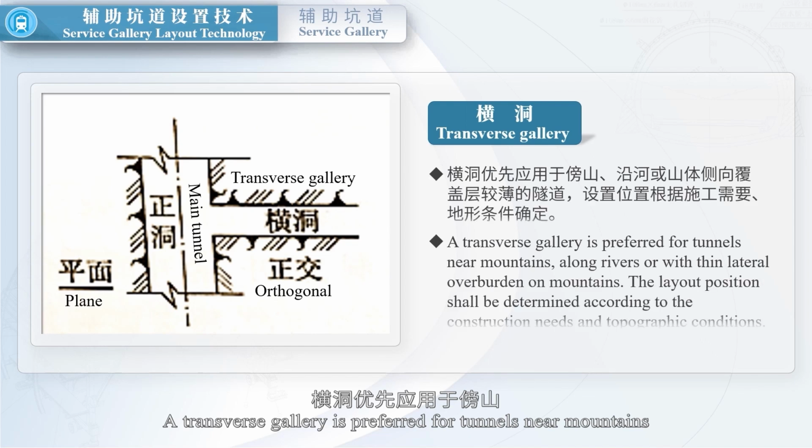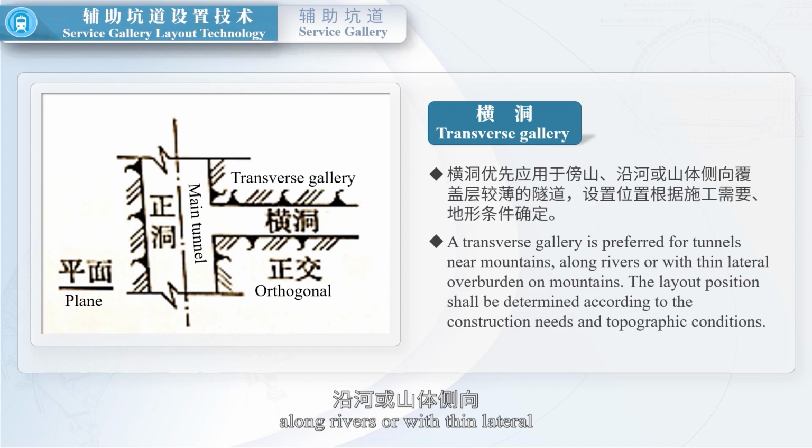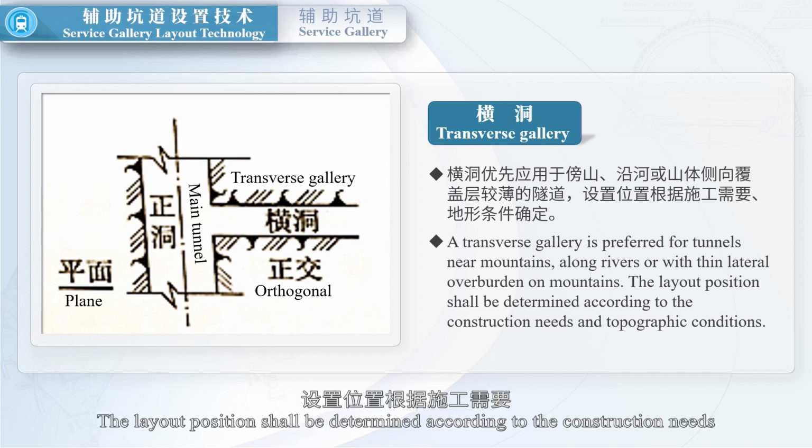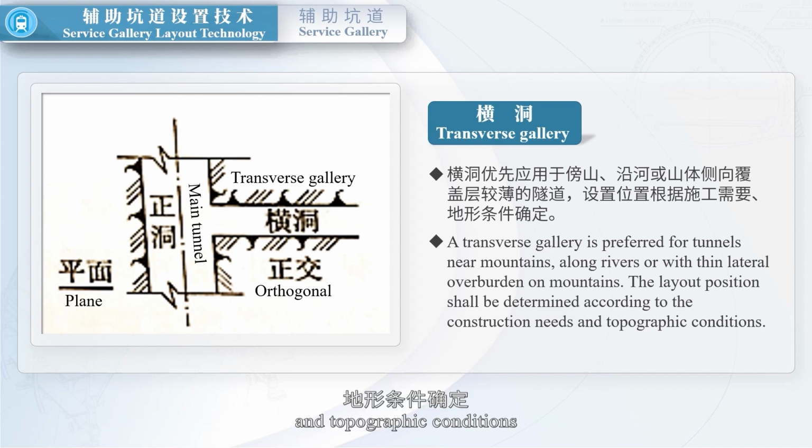A transverse gallery is preferred for tunnels near mountains, along rivers, or with thin lateral overburden on mountains. The layout position shall be determined according to the construction needs and topographic conditions.